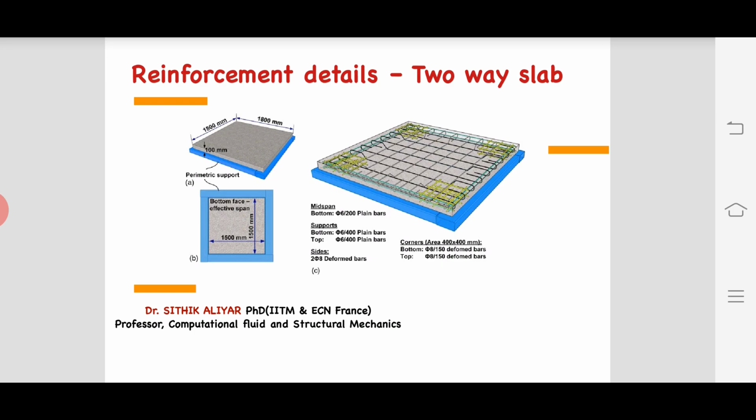If it is simply supported, it is very simple. Take an A4 sheet of paper. Assume it is a two-way slab. When you press your finger at the center, what will happen? Four corners will lift and the A4 sheet will go down, right? So it is simply supported. There is a torsion acting on the four corners. Nobody is arresting that, so it is freely lifting and the paper is going down. Okay, that is the simply supported condition.